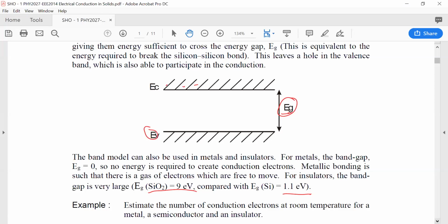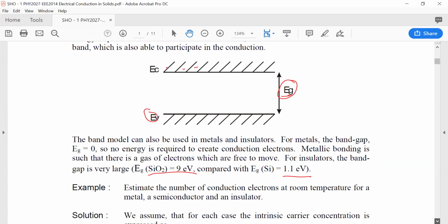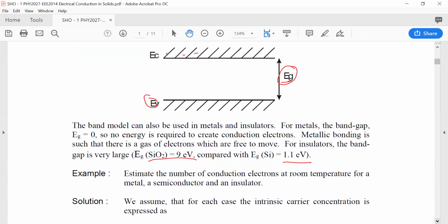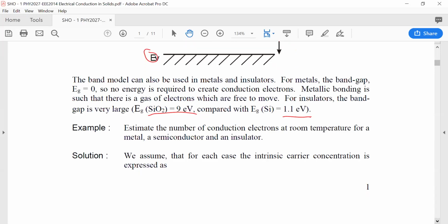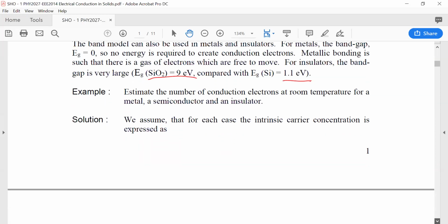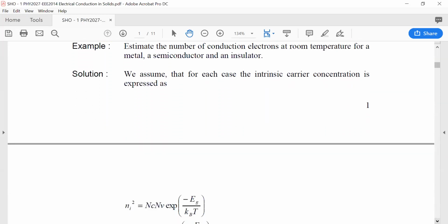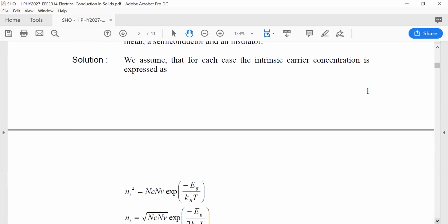So we have an expression for calculating the number of electrons and holes in an intrinsic semiconductor. In fact, we give it as an electron density or an electron concentration. And we're going to call it small n here and throughout this module. This is the expression that you'll need to copy down. So n is what we'll call the electron density, and it's measured per cubic centimetre and refers to the concentration of free electrons in the material. In other words, the concentration of electrons which are able to conduct current. And so therefore, when we calculate it, a larger value obviously means a bigger current.